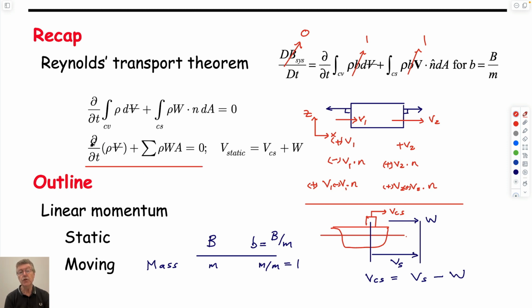Rates of change of accumulation due to a changing density going into a closed volume, or an unchanging density going into an expanding volume. So either filling up a tire and the density changes, or filling up a bucket and the volume changes, and equal to the product of density, velocity, and area. So this is momentum. This is not momentum. This is just a mass rate. So area times the velocity is meters cubed per second, multiplied by density, which is kilograms per meters cubed, gives you units for this of kilograms per second, which make it up.